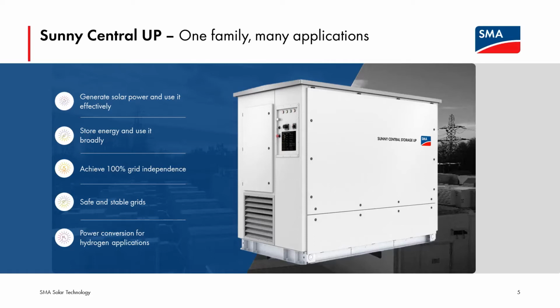The second member of the family is the Sunny Central Storage Up, a bidirectional battery inverter capable of working in traditional grid following mode as well as in innovative grid forming mode. 100% grid independence by completely going off-grid is no problem, and adding services like synthetic inertia or additional short-circuit current contribution provides benefits for safe and stable operation of grids. The latest family member is a specialist in power conversion for hydrogen applications. The SMA Electrolyzer Converter Up is a grid-friendly rectifier for powering various types of electrolyzers.